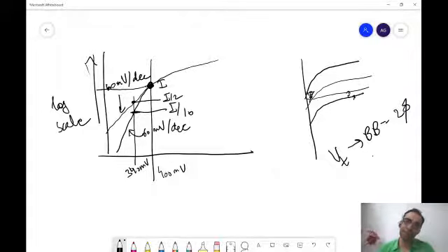We said two devices have the same VT, but their subthreshold slopes are different. This is what it means: they have the same current at VT. Now the subthreshold slopes are different. What happens to the current at 340 millivolts? Are you able to see this, Gagandeep? Right, sir. So out of 60 and 100 millivolt per decade, I would want 100 millivolt per decade, why? That has more leakage. Sorry, right, 60 millivolt per decade. No, there on the silicon, I want as steep a slope as possible.